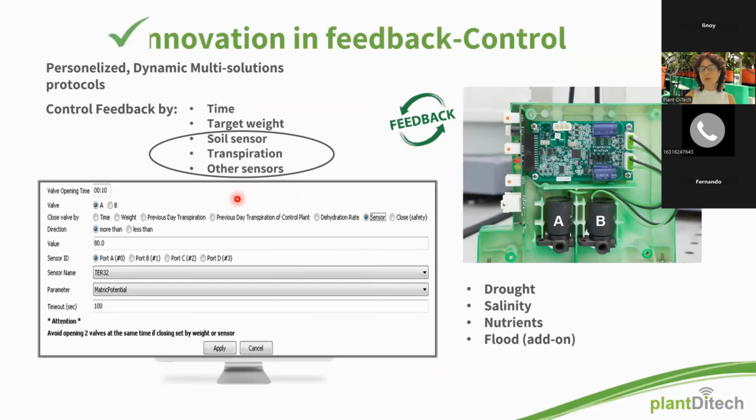So how do we do this with our system? We use a feedback methodology with the help of the electronic card in our controller. This controller sits next to each and every one of the pods. It can control two different solutions to be applied to the plant. You see tap A and tap B. These are the taps that open and close the irrigation. And we can add different sensors here.